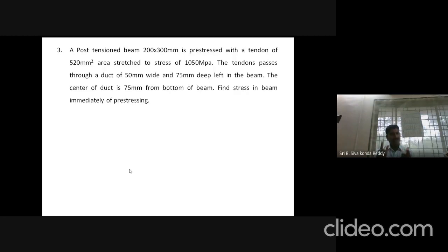We have the same force, same cable, same steel, and with some intelligence we are locating the cable using concepts of eccentric pre-stressing. So the first example showed differences between eccentricity 0 and some eccentricity. The second example was a pre-tensioned beam. The third example is a post-tensioned beam.